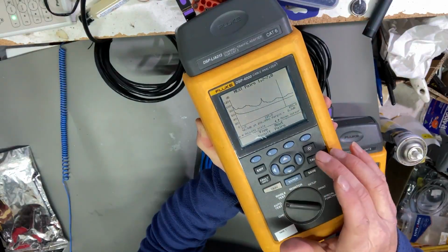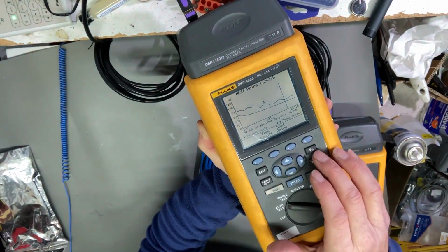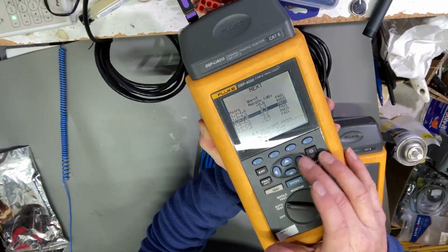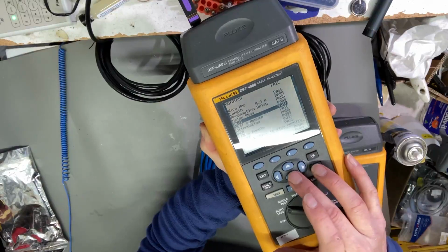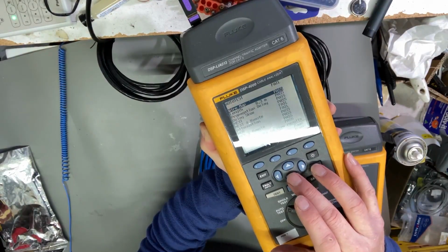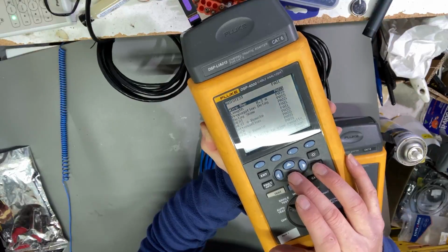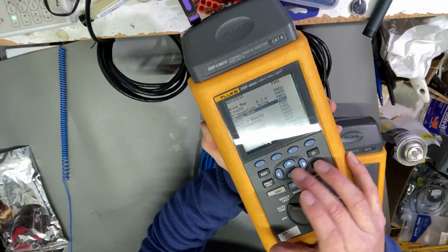That's frequency along the horizontal scale there. If we look at one of these other tests, it's kind of like a cable X-ray, where it sends a pulse down the cable and then listens for the reflection of that. So more like a cable radar than an X-ray, I guess.